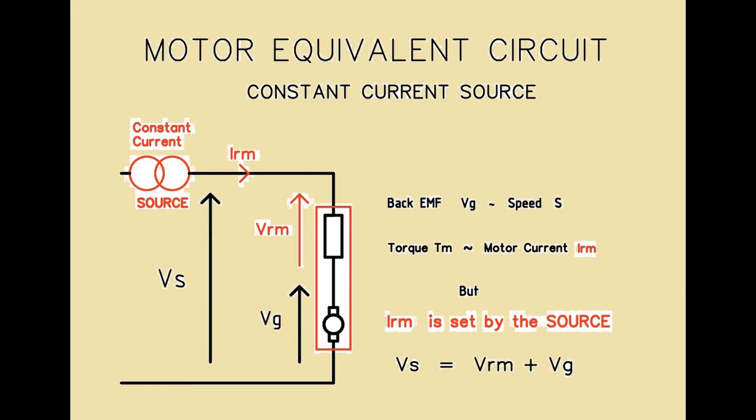There are other possible control strategies. Let's consider current control. If we start off from rest and gradually increase the current, i.e. torque demand, nothing will happen until the value exceeds the effect of static friction. Then, suddenly the train will begin to move. However, since our current demand is greater than what is required to balance kinetic friction, the train will begin to accelerate. Force is mass times acceleration.